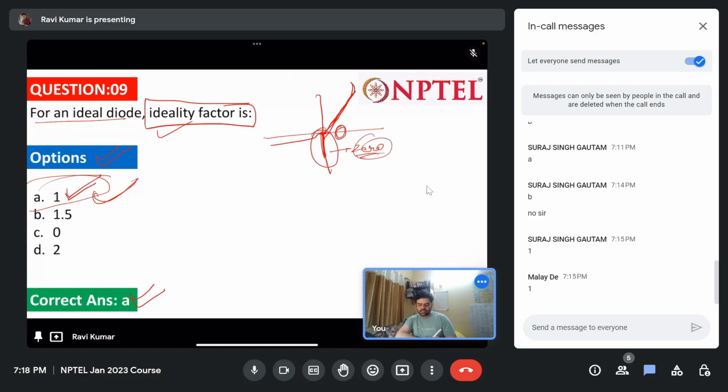And in this curve equation, I equals I naught exponential QV by nKT minus 1. This n represents this ideality factor, and I'm giving you a homework which is very interesting.